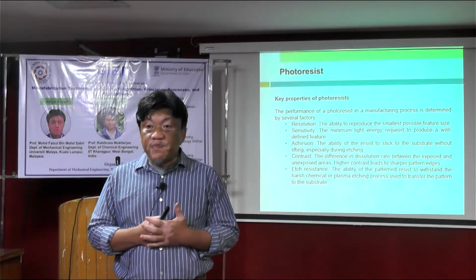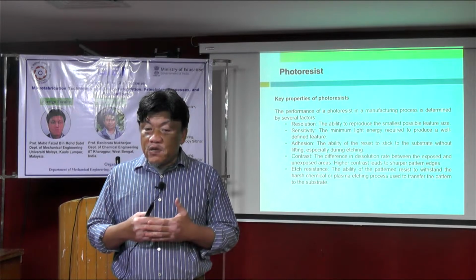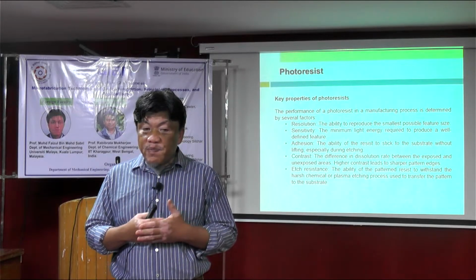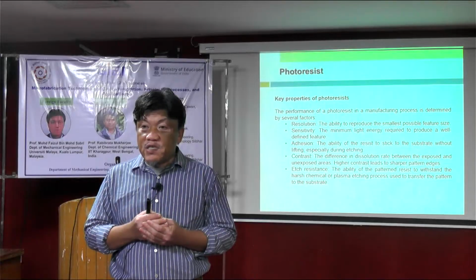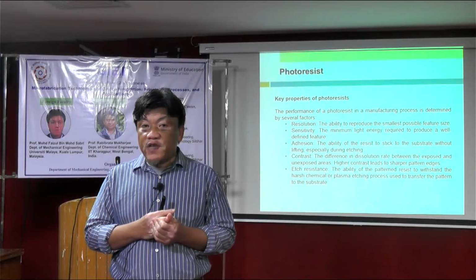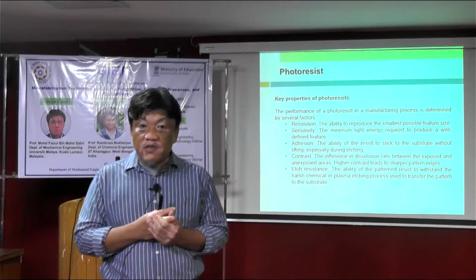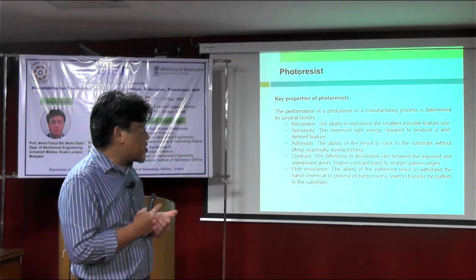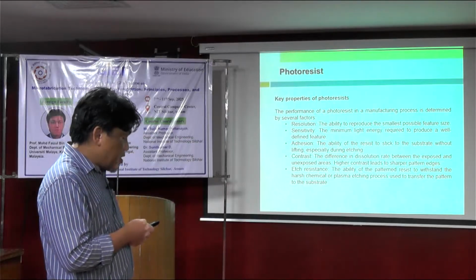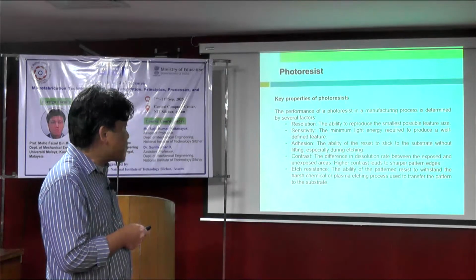The longer you expose, the more your pattern won't be as intended, meaning it might go beyond the size that you have designed, because the longer you expose, the more light scattering might happen. So you want to have high sensitivity to a certain extent.